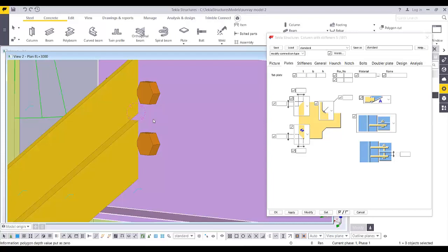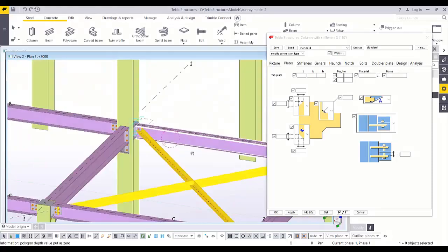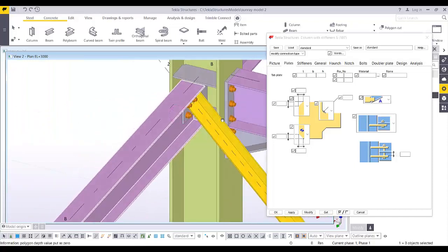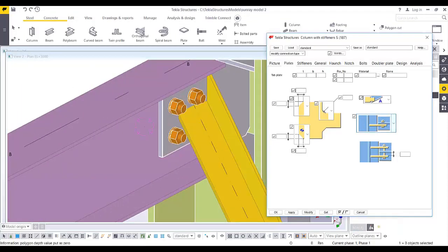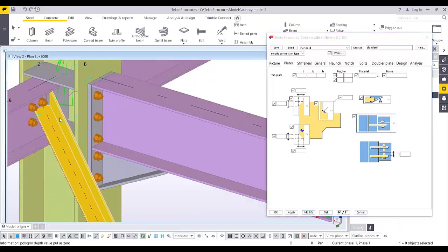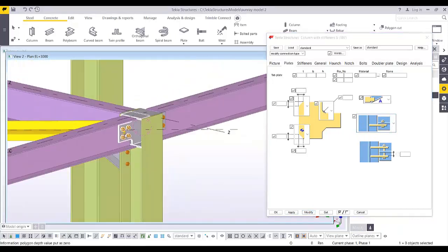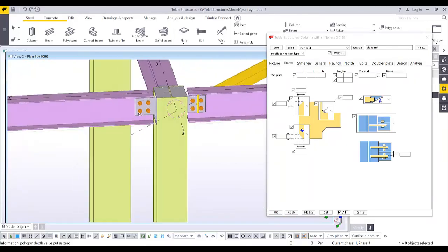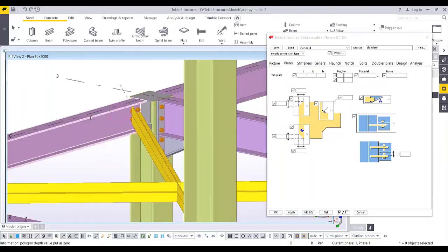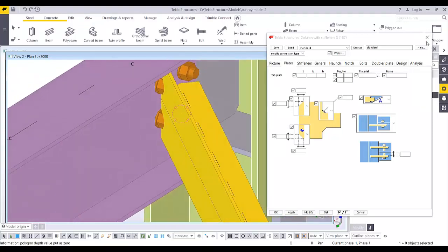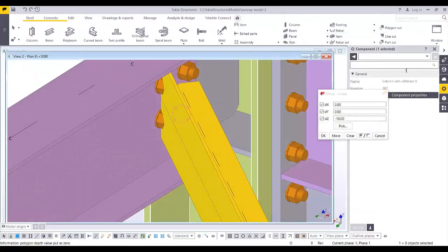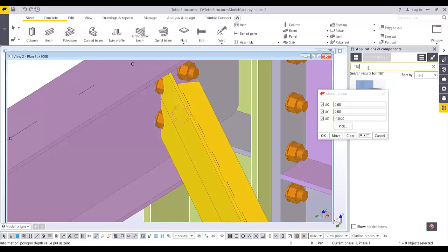It happens. The gusset plate is in between the bolt. Okay, and you just need to increase the bolt. Anyway, instead of changing the connection, all we have to do is to change the position of this to the other side. So that one is okay. So this one is already on the other side. Right? So now let's add the gusset plate for this. We'll just use the number 11.